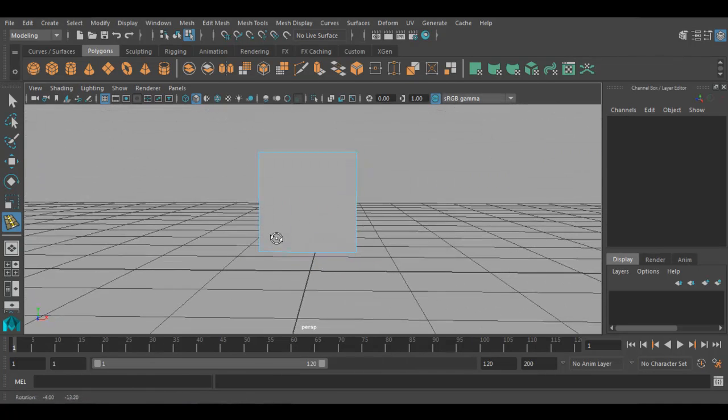If you want to place a vertical edge on this surface, so select any of horizontal edge over here. I'll hold the left mouse button. You can see there is a dotted line which I can see. Now if you are holding a left mouse button, you can see the loop is coming, and you can place this particular edge on this surface from this point to this point.